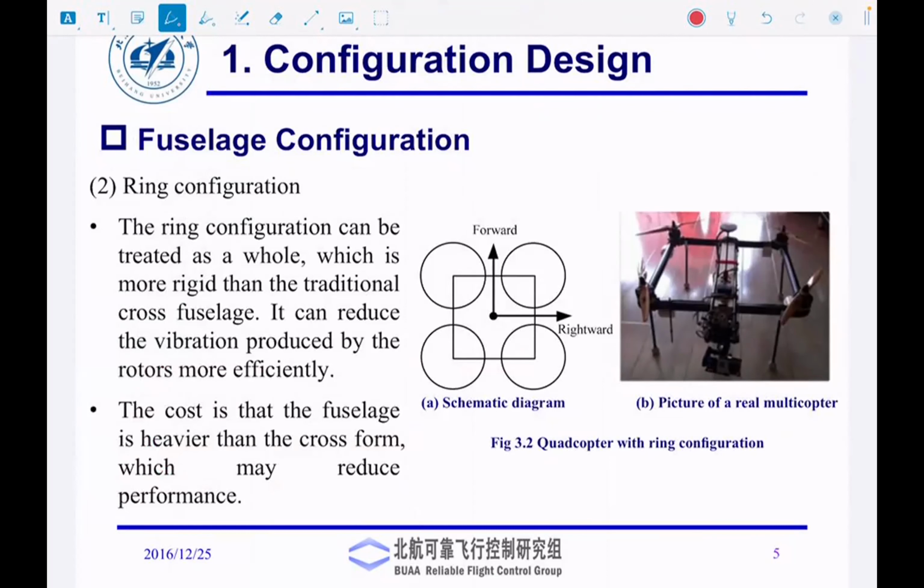and you can have a rectangular fuselage that is shown on the right hand side, or you could just have the booms crossing each other. The problem with that type of fuselage is basically it adds to the weight, and quadcopters are very inefficient for flying, because for hovering you actually have to supply the battery voltage and current. So if you have a fuselage that is aerodynamically not efficient, you are going to spend a lot of energy just to maintain a stable hover.